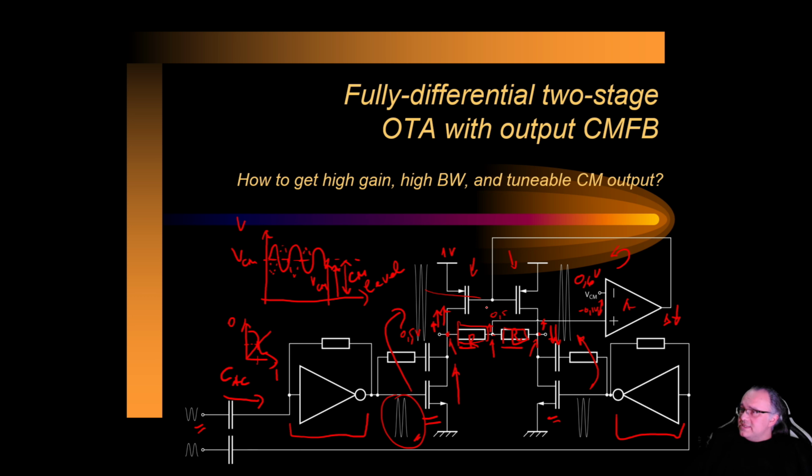So this will go down. As this goes down, this node here will go down with this delta, which increases the source gate of this load current sources of the pmos transistors, this transistor and this transistor, and they will source more current. As they source more current, then this node will go upwards, and this will go upwards because then this current will be more than this current, which is for the nmos transistor.